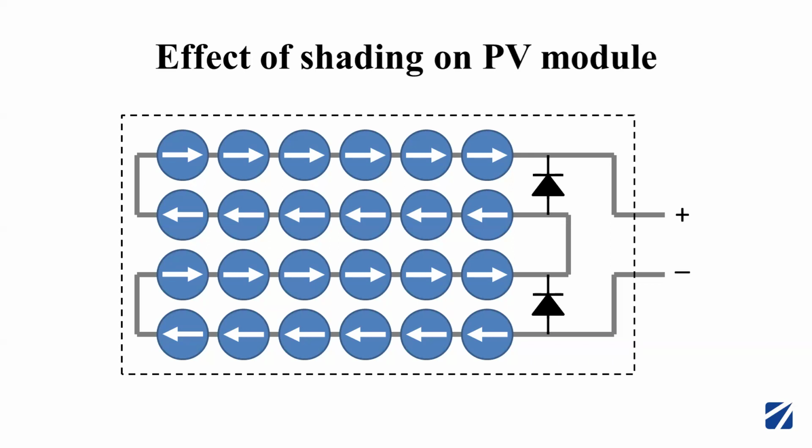So all these things we will check before installing the rooftop, which we call a site survey. Whenever we install a PV system, we need to take care that there are no shades falling on the system. We ensure that maximum solar radiation is falling on the system without any obstructions. Also, when we arrange the solar PV modules in rows, we need to take care that they are distanced properly, because of mutual shading, like one module casting a shadow on the next module. So we need to maintain a pitch distance between these rows.